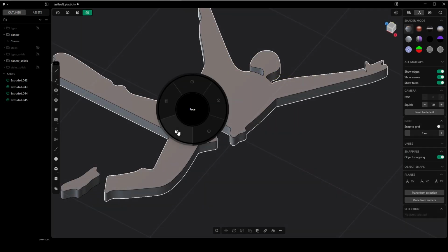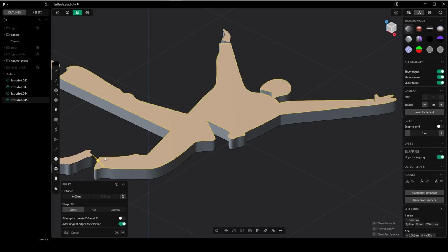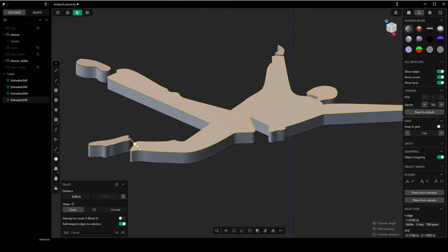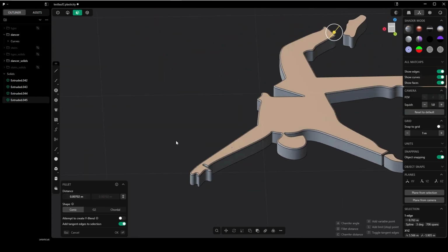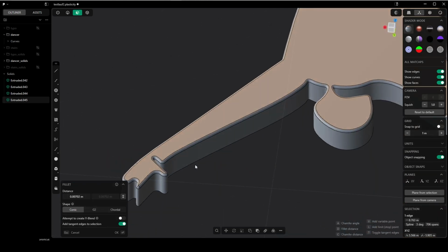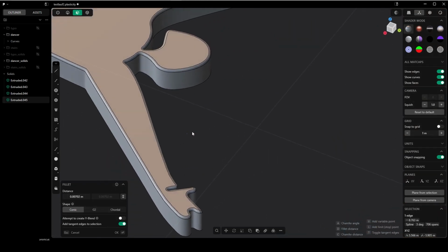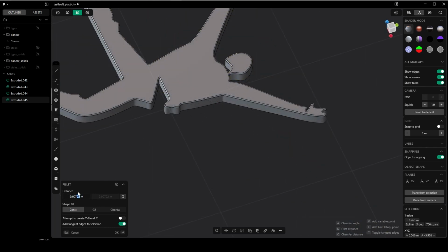That's okay, I think. And let's select these solids and isolate them, Shift H. Now we can select this face and press Ctrl 2. It selects automatically the edges of the selected face. So if you press Ctrl 2, you have automatically this selection and you are ready to fillet. So let's try our fillet. Before pressing OK, let's just check how it looks. I think 0.007 is okay, because I have to take into account this situation here. If I go further, that won't look good. So let's give it a round number, 0.007.